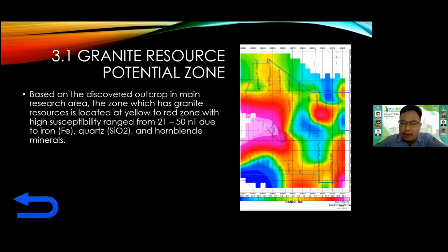As you can see on the left side of the map, there is an area with purple color. In this area, purple showed because there is some exposed granite which makes disturbance in the reading and causes the data to be spiked.